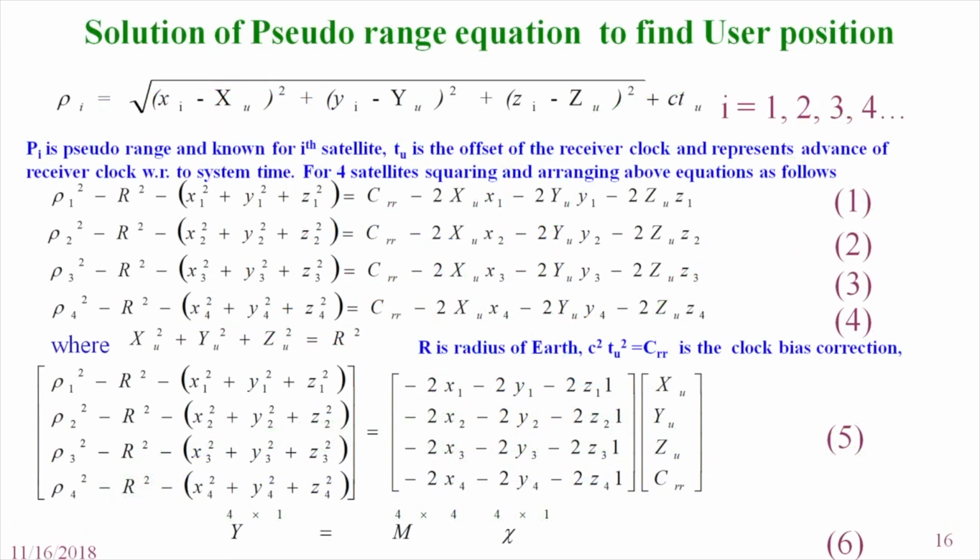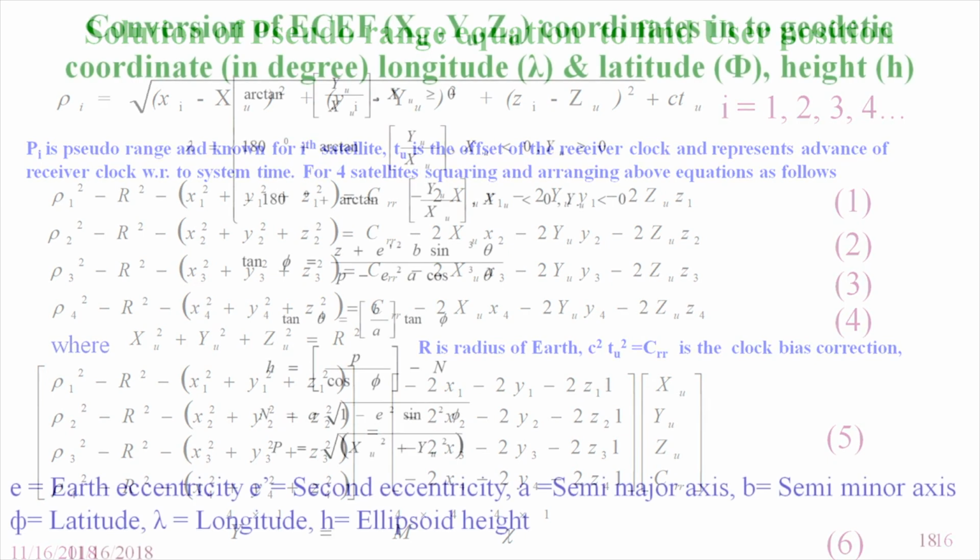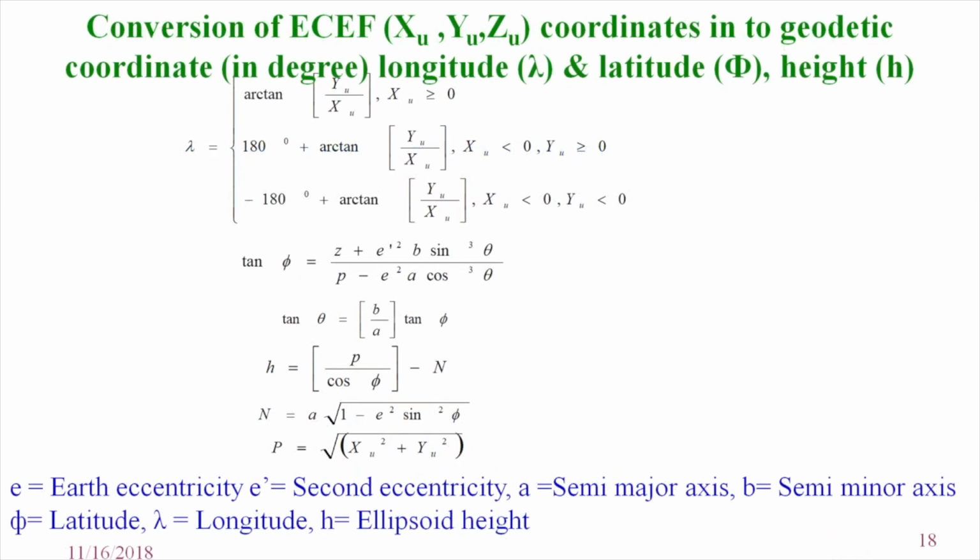So, these are the equations. Different equations are used to calculate the location, because it gives the range, the pseudo range. By solving the equations, we are able to find the user location, because it gives x1, x2, x3, y1, y2, y3, z1, z2, z3, which gives a position, that is the latitude, longitude and height. So we are able to find the exact location of the station.